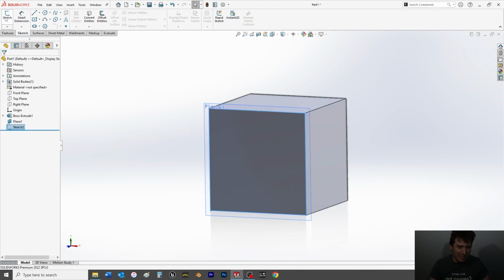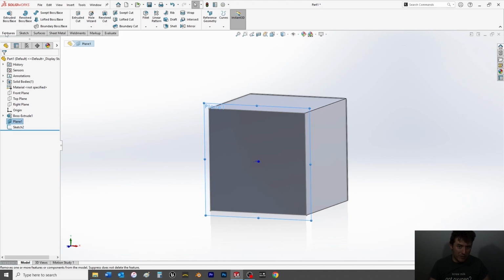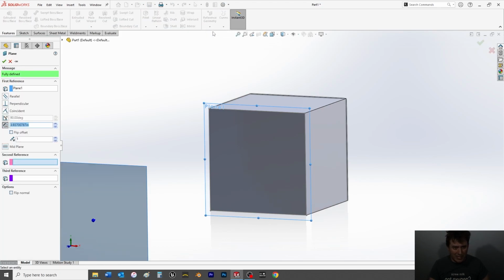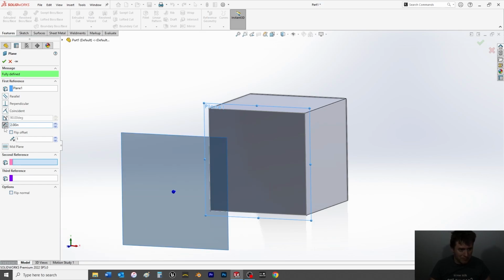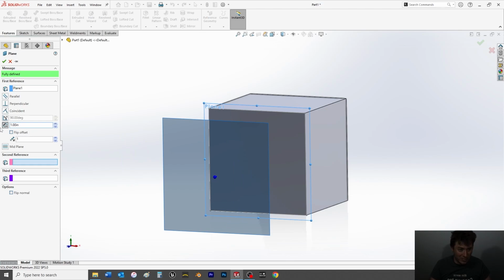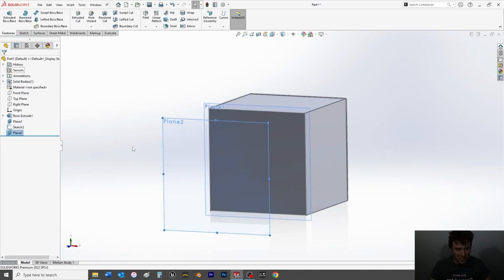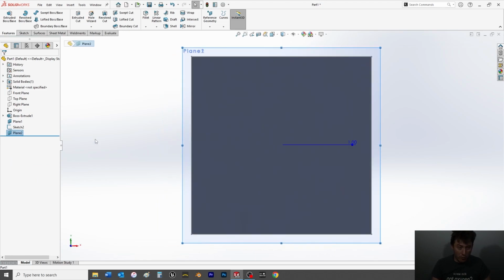Now I'm going to exit out, choose the plane 1 again, go to the Features tab, choose a reference geometry again, another plane, and there it is. There's that magical 3-some-odd inch number there. And we'll do an offset, why don't we just call it, I don't know, 2 inches. Or why don't we just keep everything on the 1. So 1-inch offset. The next thing we'll do is make sure that plane 2 is selected, Control 8, normal to.